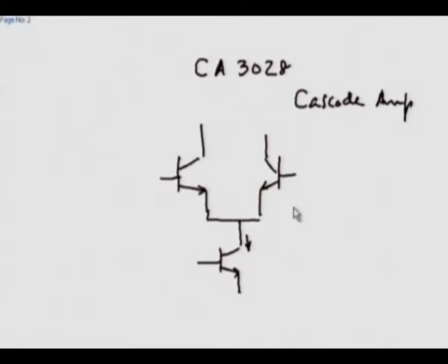Now these transistors here are chosen to have quite high frequency response. So the first transistor can be designed as a CE amplifier by putting external components outside, and you could design the second transistor as a CB, a common base, again by appropriately biasing here.